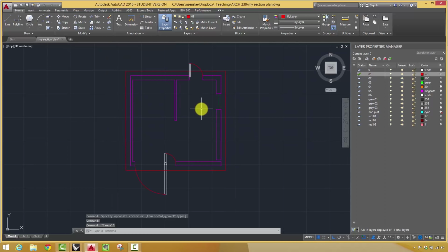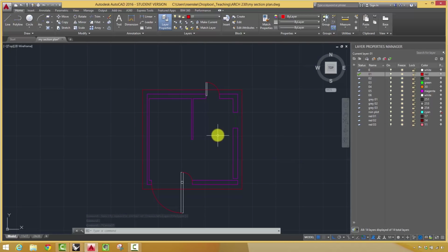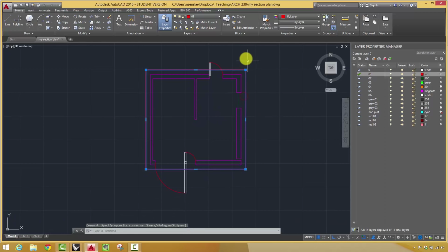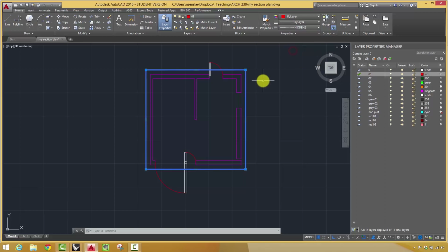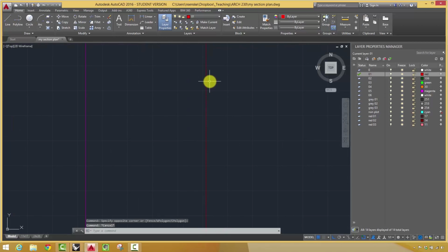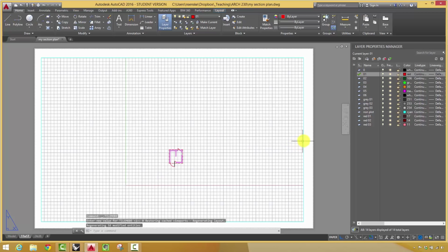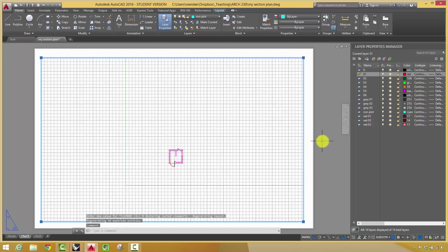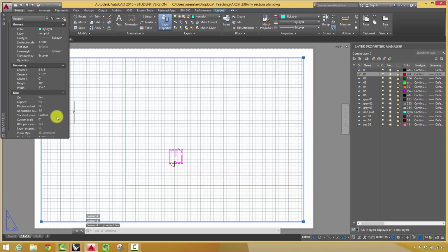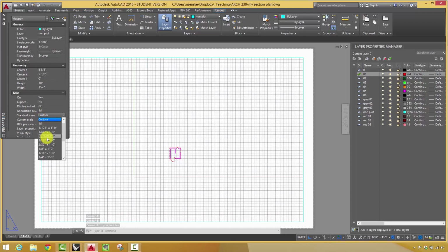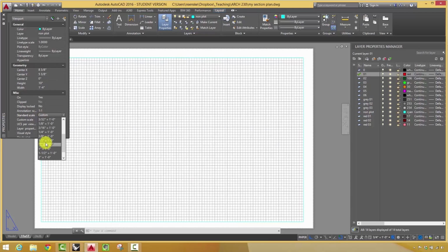Fine. Okay. Let's see here. The other thing that I would do here is just go ahead and make this particular one a hidden line, and you can't really read it that well. Let's go to the layout, and then we go to properties. Let's figure out a scale for this thing. I think it probably wants to be 1/4 inch, but